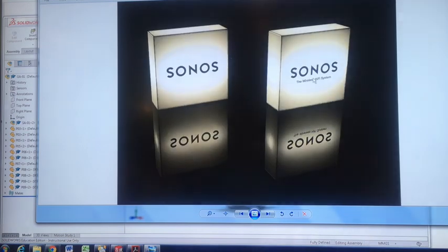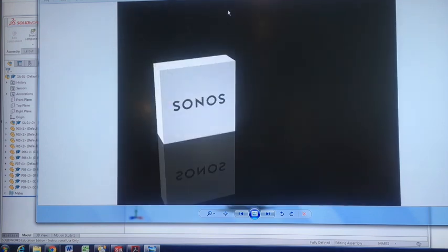So instead, you need to change that material to, in this case, a wax, semi-translucent. And then we modeled just a cylinder on the inside of that object, so that object's hollow, a cylinder on the inside, and add the light to the cylinder. That then gives off the light and gives the effect of a globe in the center which gets darker towards the corners. So that looks a lot more realistic compared to that, which just looks like a white square.